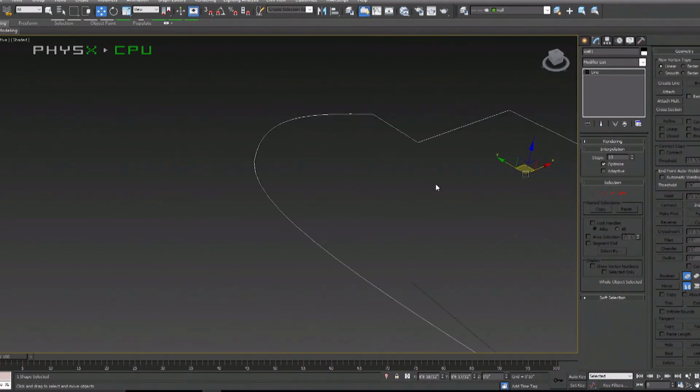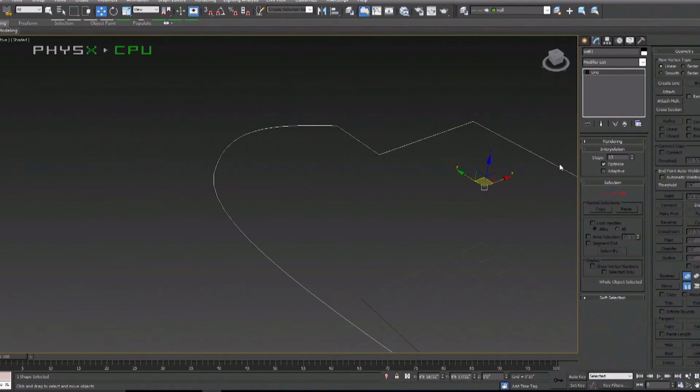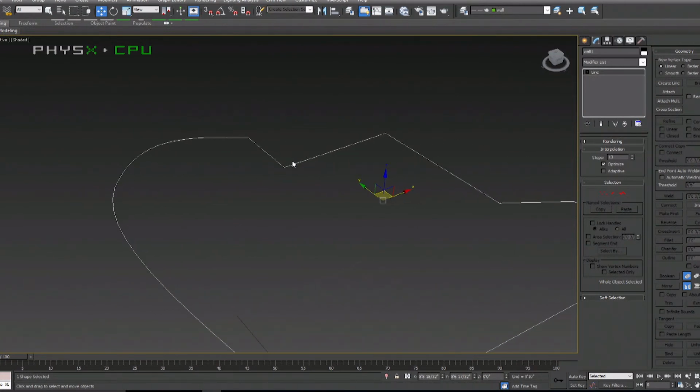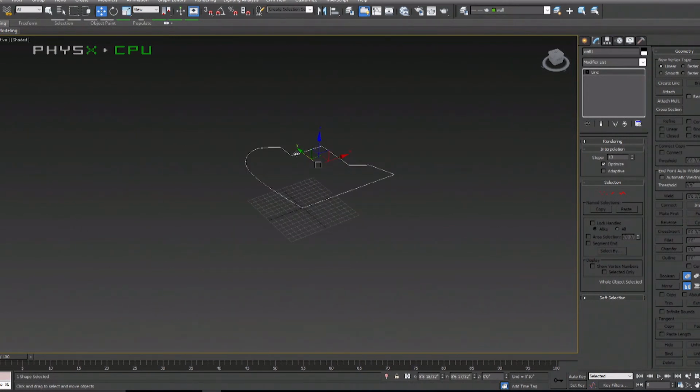And the reason they did this in 3D Max is actually to allow you to control the amount of RAM that you're going to use, because if you have more steps, that means you use more RAM. So basically for something like this, you don't need many steps, so you keep them at 6 or whatever. But if you have a shape that has curvature, it's better to have it with more steps like this. So this is just the first look at 3D Studio Max,